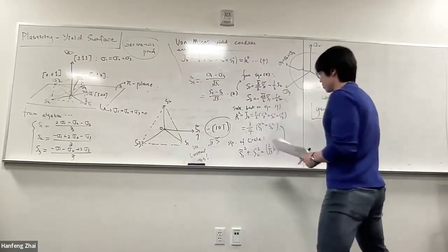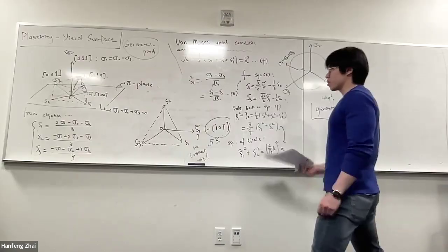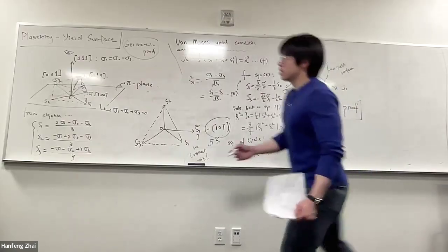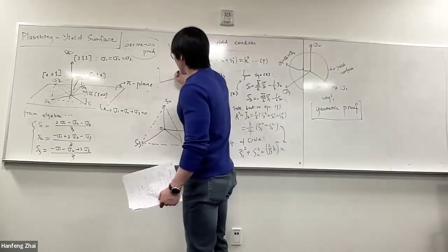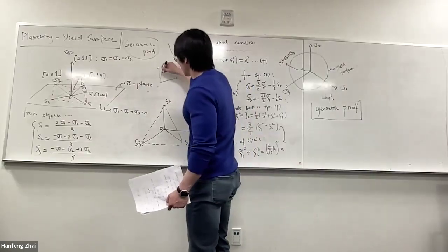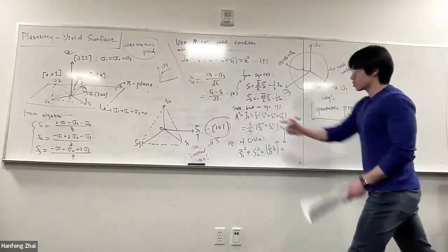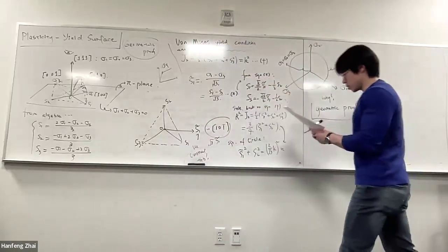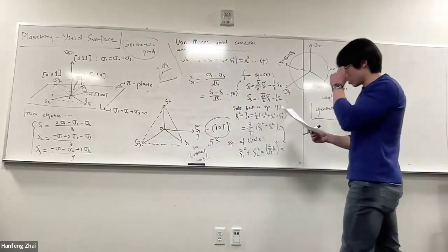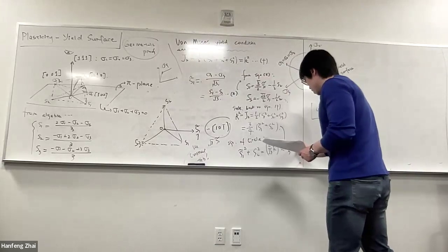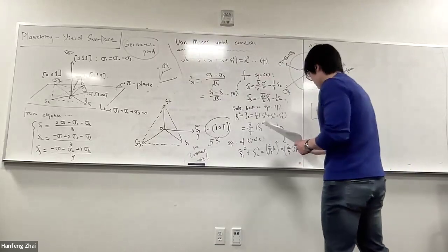And further, from the lecture, you probably already know the correlation between k and yield stress. Just in case I didn't define a symbol, the yield stress is sigma y. So you substitute k and sigma y using the square root of 3 correlation, then you have 2/3 yield stress squared.